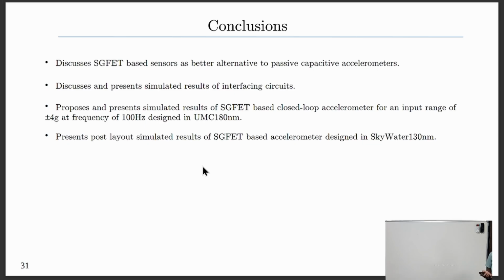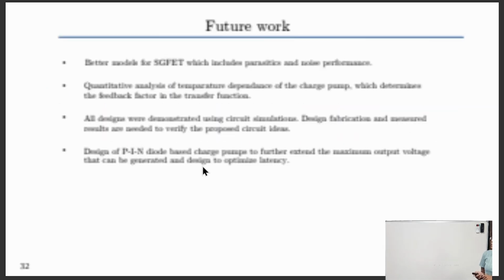These are the conclusions from my work. Here we discussed that SGFETs are a better alternative to passive capacitive accelerometers, and we also presented the simulated results of interfacing circuits and the closed-loop accelerometer. The closed-loop accelerometer simulated results for 2 different inputs were also presented, and also post-layout simulation results for our design in Skywater 130 nanometer were presented.